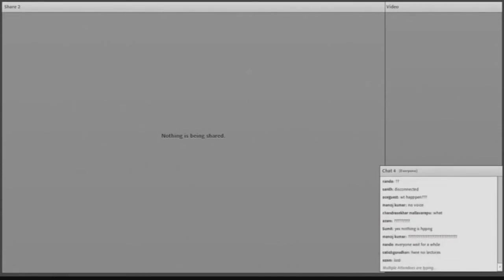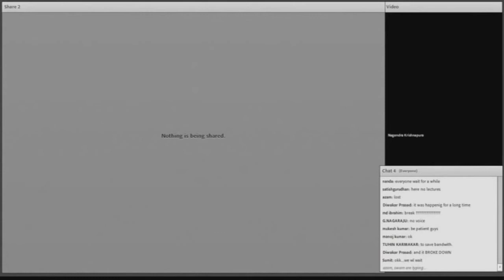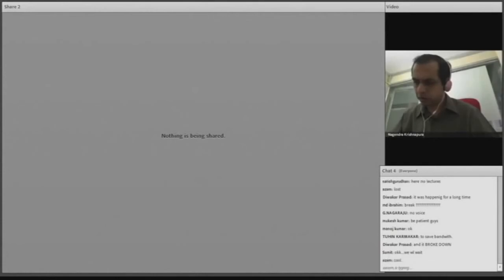Now, when I have a wire from A to B, and mark an arrow from A towards B and write 1 ampere, that means that a positive charge of 1 coulomb has gone from A to B in 1 second. The exact same situation can be depicted by having a wire with an arrow drawn from B towards A and with minus 1 ampere marked on it.